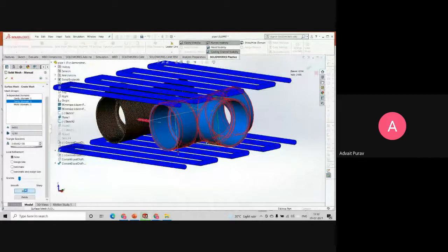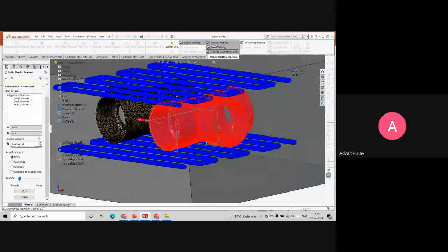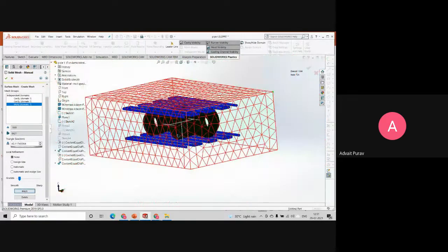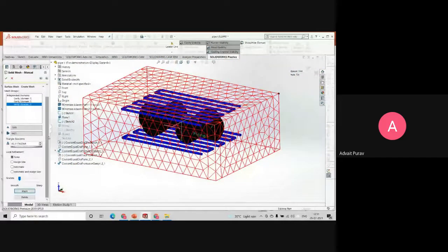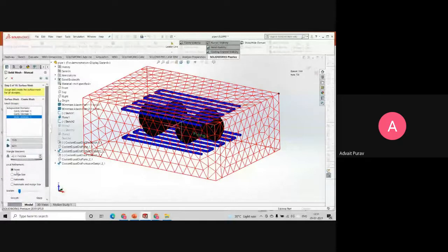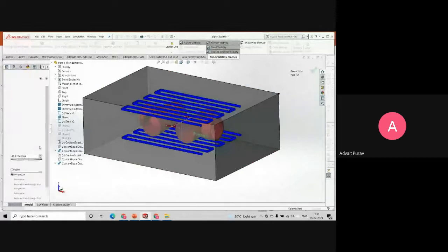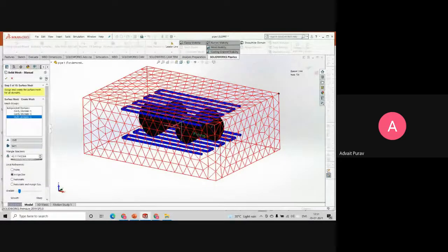And this is 2.65 mm; I assigned this mesh size here. And for the mold, we'll keep the size of 42.11 that the software is suggesting. You can reduce it as well, but right now I'm not doing it. I didn't assign size, okay. So now we'll go further.